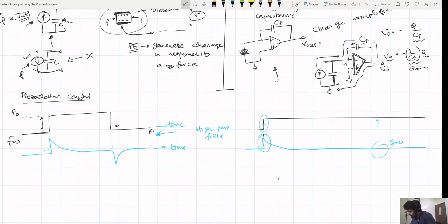In fact, if you remember, a simple example of a high pass filter is this circuit, right? What will happen if you apply a step input to this? Let's assume the initial charge on the capacitor was 0. What will be the output VR if the Vin went from 0 to V0? What will VR look like in this case? It will be a decay. It would gradually increase from 0. Like this, is it?